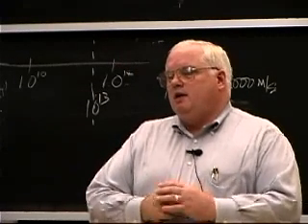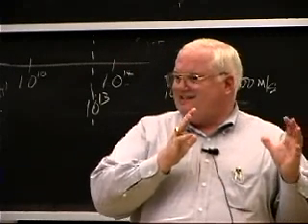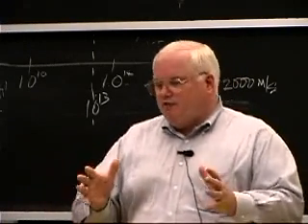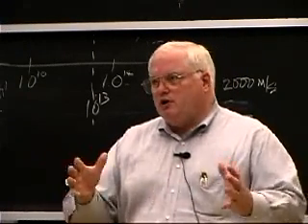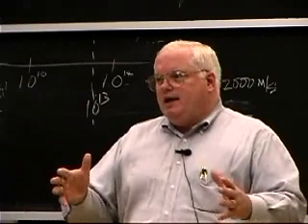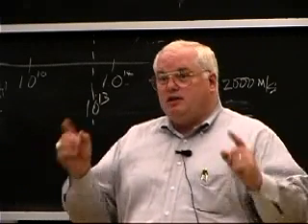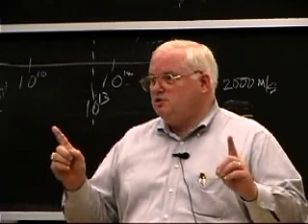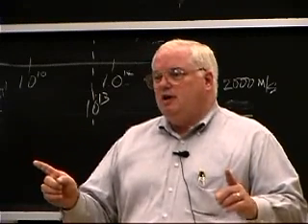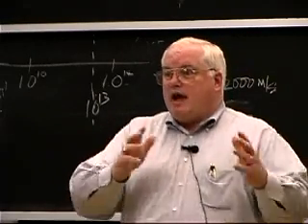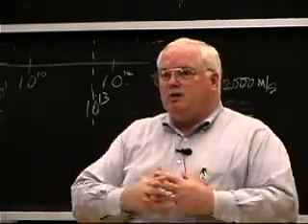Now, there's sometimes confusion between design verification testing and proof load testing. In design verification testing, I actually build a structure, I load it up to 125% or 150%, and it doesn't fail, and I say, that's a good design. It didn't fail under the loads I expected it to see in service. I've had people get confused and say, well, that test proves that all the other 100 I built are good.